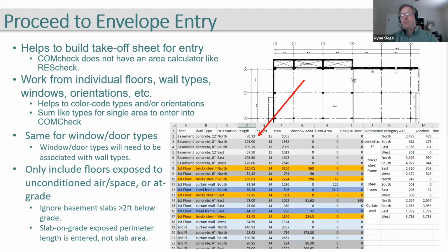something that's very helpful that we find is for designers to build takeoff sheets. And you'll probably end up having to develop your own because COMcheck doesn't have an integral one at this point in time. Again, as they develop future versions and update the web entry, they may add some additional features, particularly something like this, which is commonly found in REScheck, but not yet available in COMcheck.